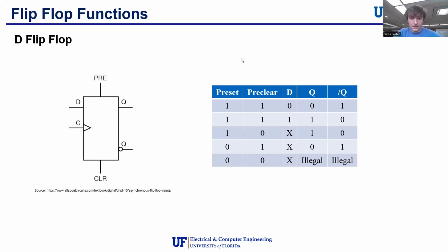Okay, there we go. So if we look at only these two rows, we can see that when the input is 0, the output becomes 0. And when the input is 1, the output becomes 1. In this way, we know that the D flip-flop works, that whatever's going in will come out. So we can look at the next state truth table, and whatever we have as our Q plus is going to be what we route into D, which we'll use in, I think, part 3 of the lab. So this is extremely useful because it allows us to pretty easily make what's going into the flip-flop.